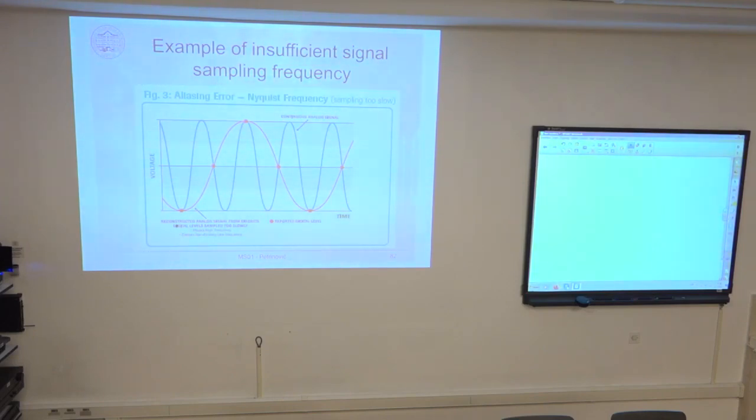And obviously, one element that is needed to ensure that no such signal like the blue signal occurs at the input of the AD converter is a special analog filter that is called an anti-aliasing filter. It is a low-pass filter. Its only function is to cut off the band at half of the sampling rate. So after this highest frequency of half of the sampling rate, the energy of the signal must be zero.